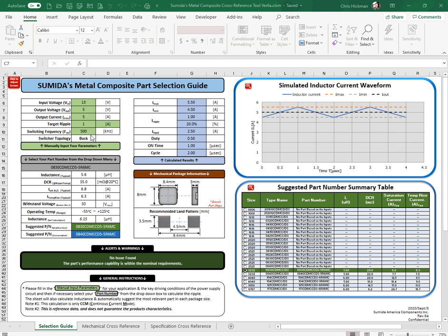This sheet will only do buck or boost in continuous current mode. Unfortunately, this sheet will not work 100% correctly for discontinuous mode switchers or buck boost switchers. Please note that as the user inputs their conditions into the green area, the sheet will be auto-calculating on every input, but the true results will not be done until the user inputs all their circuit-specific parameters.